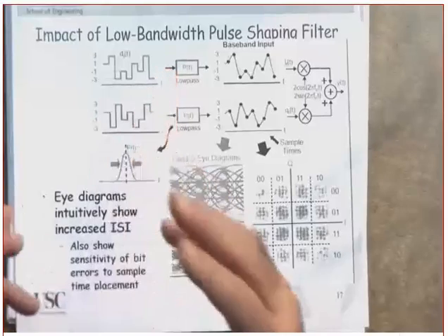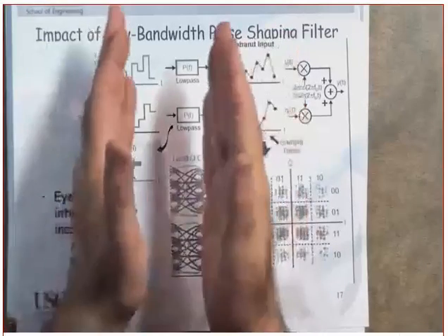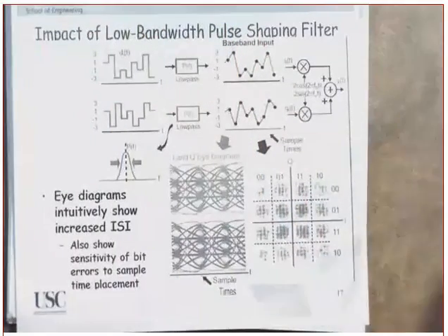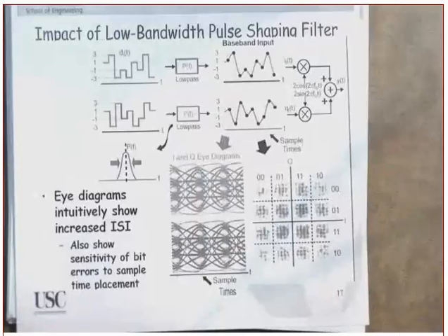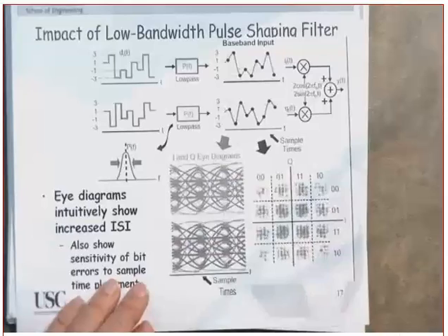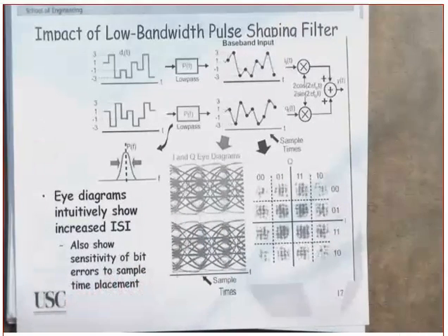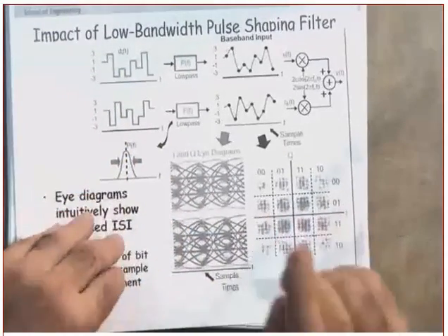Okay. This is the effect when the bandwidth is low. I want you to see the trade-off. If you make the bandwidth wide instead of narrow, will the eyes be cleaner? The eyes will be cleaner, but at what expense? On the noise side, the noise will be higher. Why? Because the larger the bandwidth, more noise power will go into the filter. So you get those things in the middle, those things that I was just telling you about.